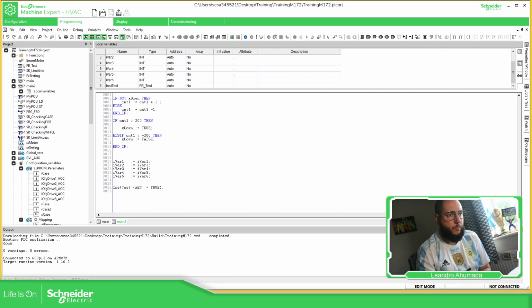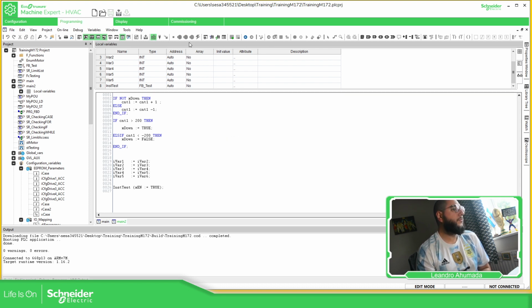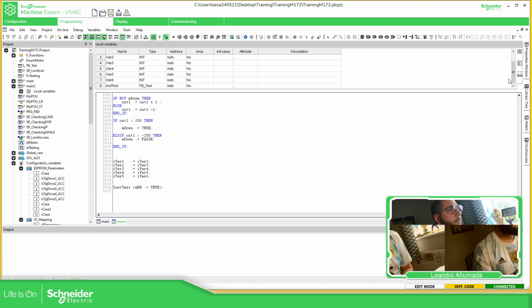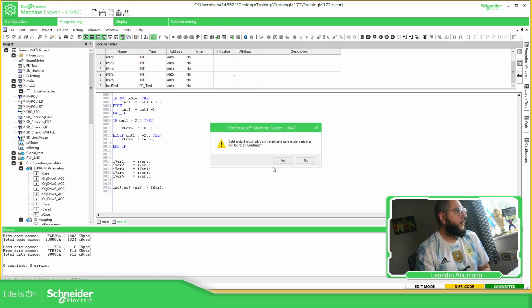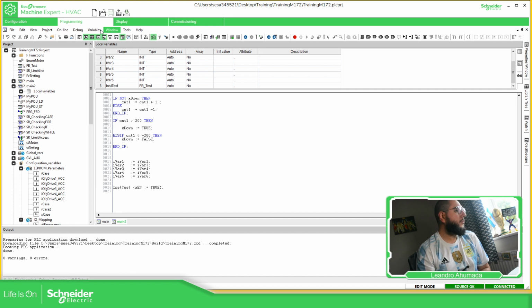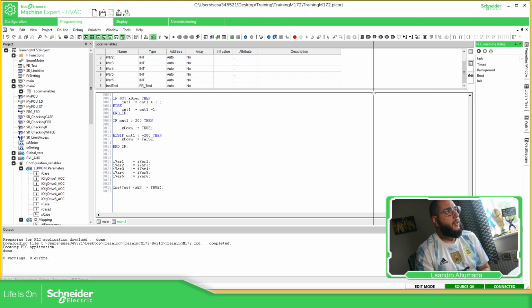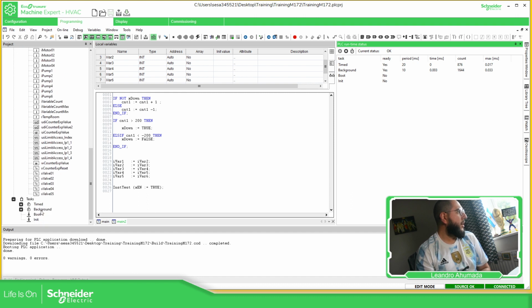So as I mentioned before, I barely use it. Let's open the simulation so I can show you this. I'm connected with the simulation. Now we need to open that tool window, PLC runtime status. You can see over here what I got. If I press this one, it will start monitoring everything. I don't know if I have something in the boot in it. No, there isn't anything, but you can see here the counts and then the max time for each one.